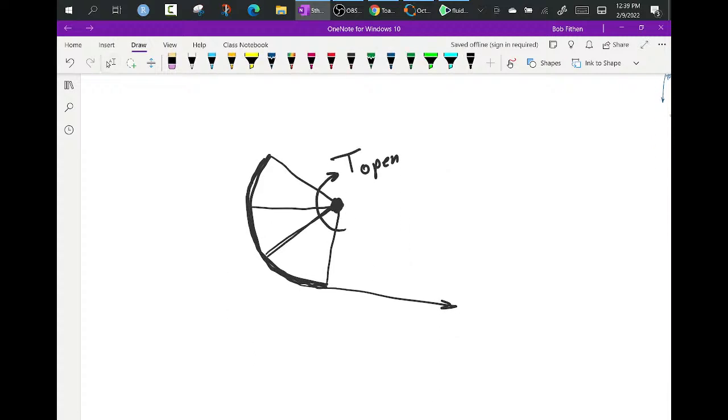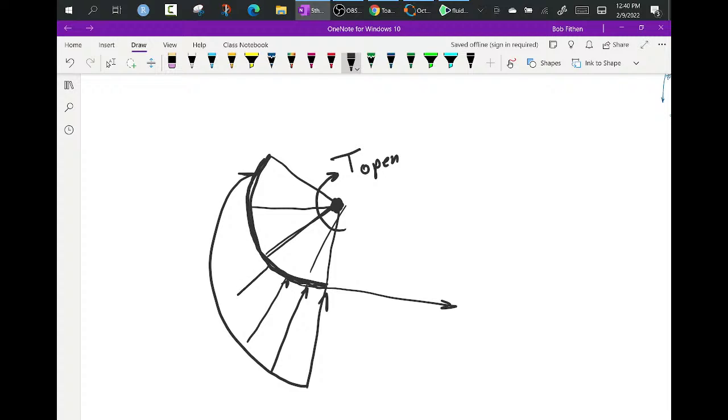Because if the water is that deep, for example, what you're going to have is a pressure profile that comes down and increases linearly. So here's your water level. But all of the pressures exactly go through the center. So they all go right through this hinge.